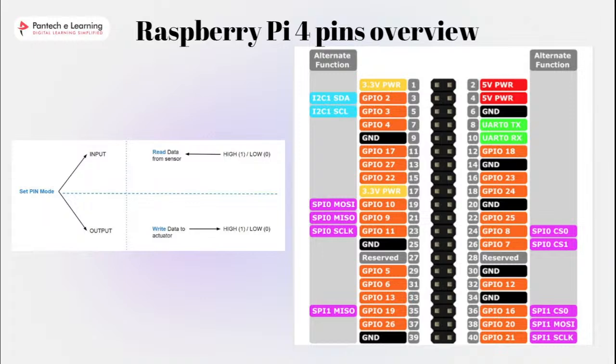And then we can talk about the power pins here. You can find 2 pins bringing 3.3 volt and 2 pins bringing 5 volt. Here 3.3 volt is on pins 1 and 17, and 5 volt is on pins 2 and 4, right? Those pins can be used to power components such as sensors or small actuators. Note that they are certainly not powerful enough to actuate motors such as servo or stepper motors. For that you will need an external power source.